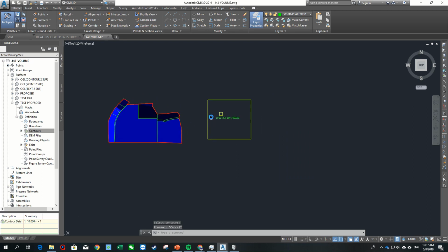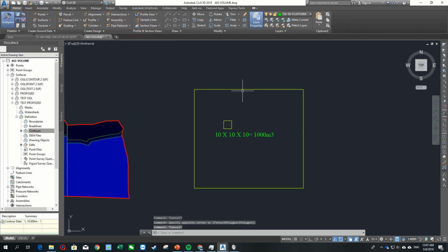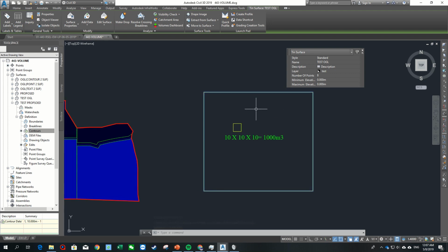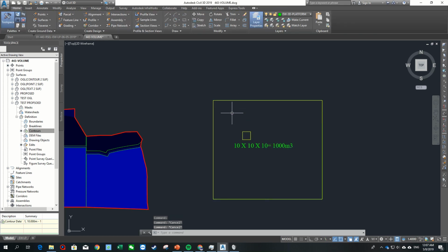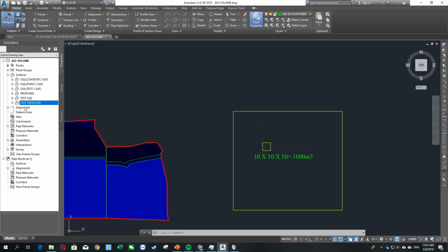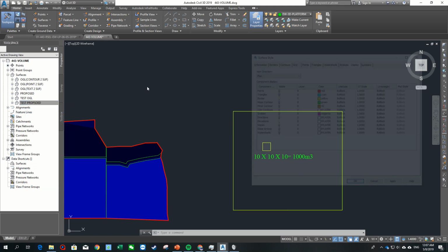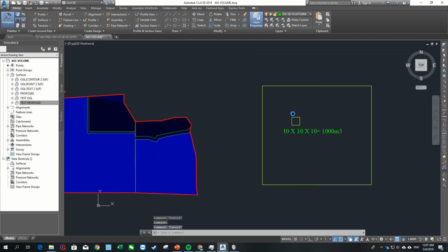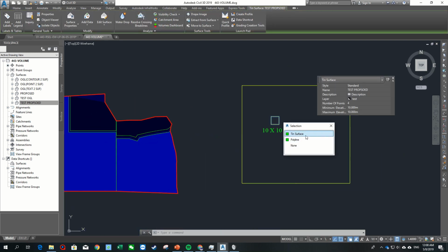Okay, now you have the two surfaces for the test. Wait, hold on, where is the surface? Yeah, the thin surface is here, but it didn't show up. Actually it is already created, but it didn't show up. It is because I didn't set the surface properties for that. Actually you can do edit, you can show, but I don't want to show, also can, because it doesn't display the elevation. It is flat, so nothing to show up. Okay, it doesn't matter as long as there is a thin surface for that.